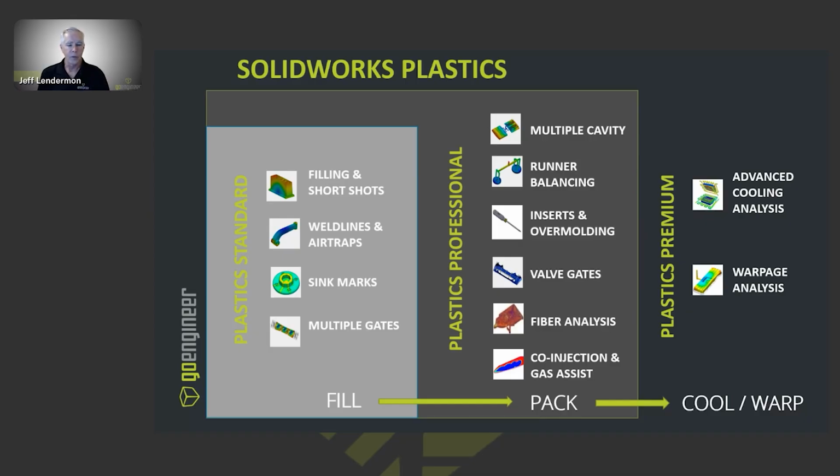It's geared more towards guys that are just designing parts and want to see how the plastic is going to flow through their part, help identify weld lines, air traps, and sink marks, and also work with multiple gate locations. So if you have a large part, you can do more gates than just one, and we can look at all of those and the positioning of those gates. We'll look at some of that today in the software as well.